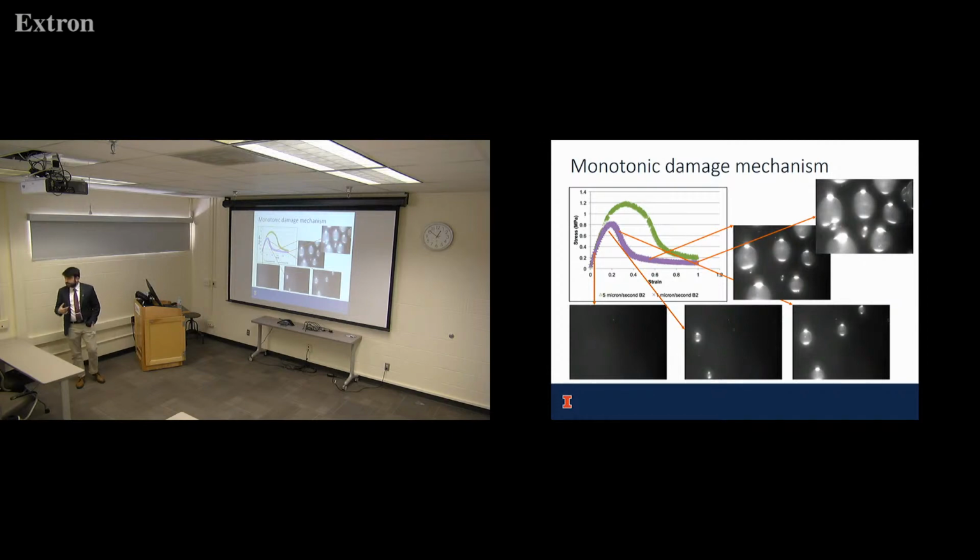So we put this as a 3-stage model. We decided that's what we can consider it. First stage is the undamaged state. Second stage is post-peak, where new cavities can form and damage is nucleating pretty rapidly. And then the third stage is when no new cavities can form. There's not enough energy to form new surfaces, but there is to grow the existing ones.